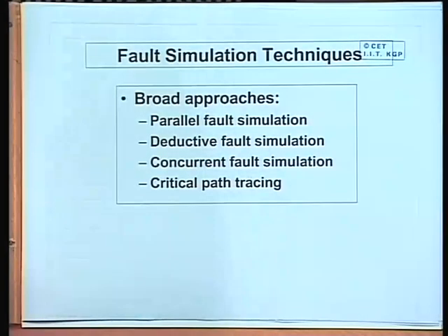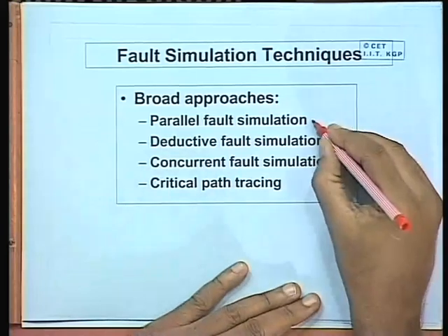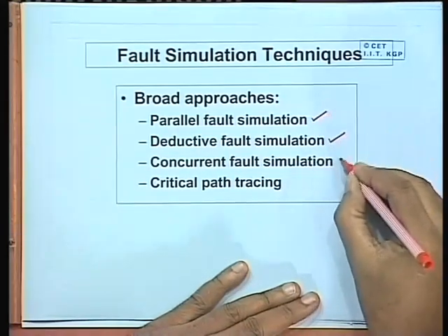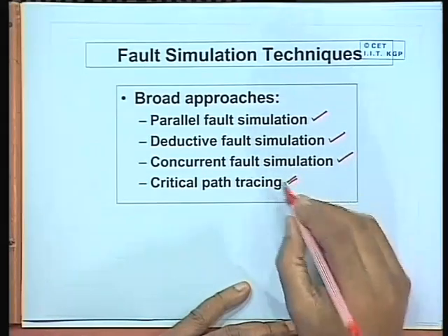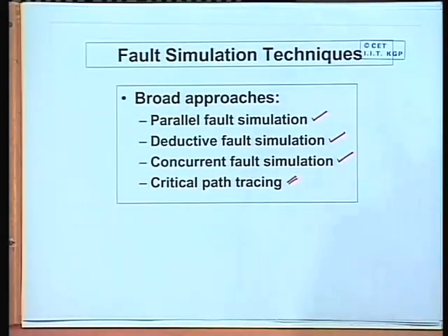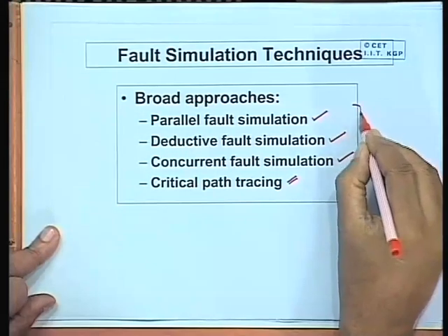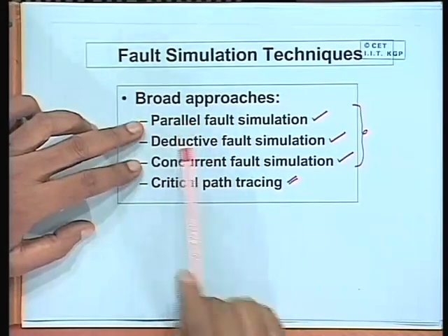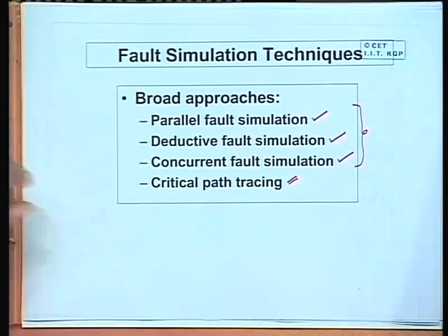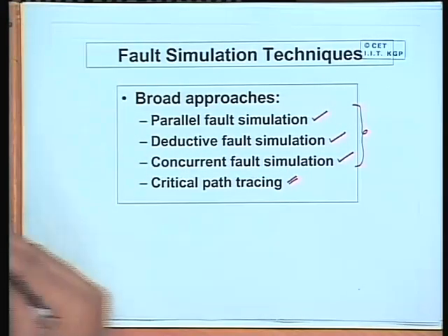Now, in practice there are a number of different techniques which are used for fault simulation. Broadly, the approaches which are followed can be categorized as parallel fault simulation, deductive, concurrent, and critical path tracing is of course a specific technique which can be used only for combinational circuits, but the first three can be used also for sequential circuits with some modification. So, let us try to see briefly what these methods really are.